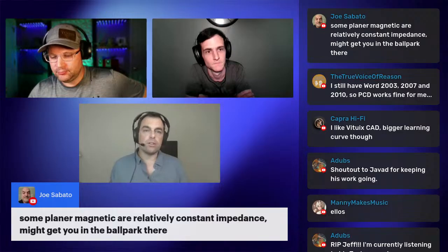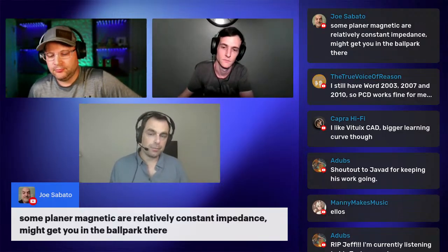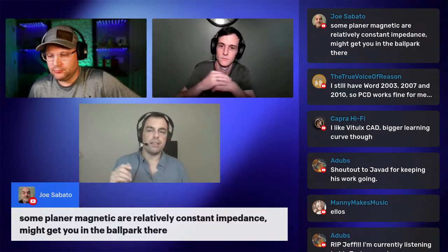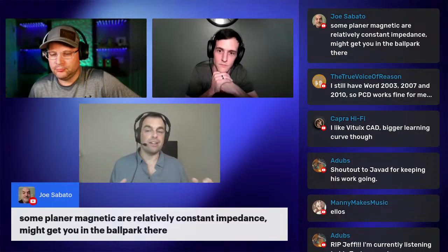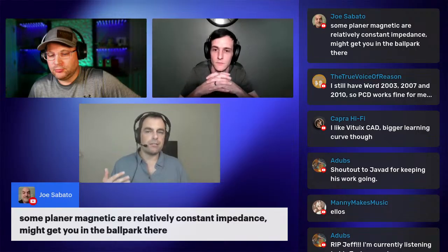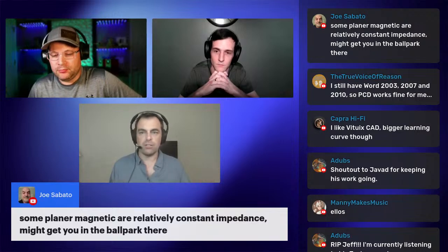Joe, I would just say to your comment, you're right. There are some drivers with constant impedance or close, and you can even do things electrically to flatten impedance, but you still have the problem of the frequency response and the phase interaction between the drivers that can't be accounted for. So the easiest way to explain it is to say impedance isn't constant, but frequency response and phase are also wildly changing all the time.